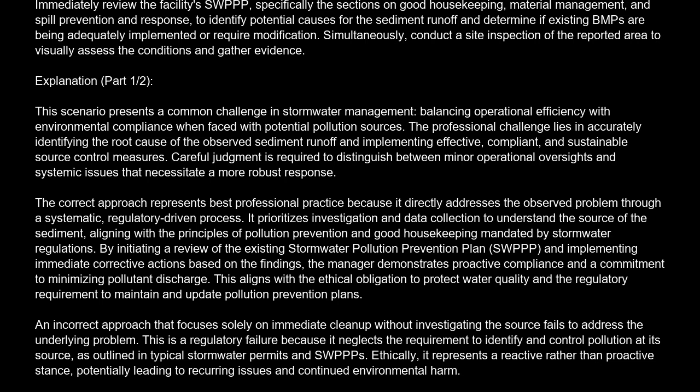The correct answer is C. Immediately review the facility's SWPPP, specifically the sections on good housekeeping, material management, and spill prevention and response, to identify potential causes for the sediment runoff and determine if existing BMPs are being adequately implemented or require modification. Simultaneously, conduct a site inspection of the reported area to visually assess the conditions and gather evidence.